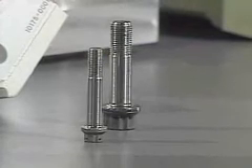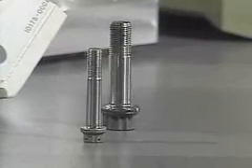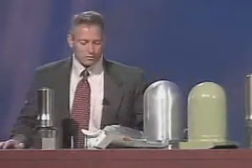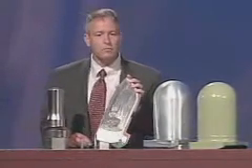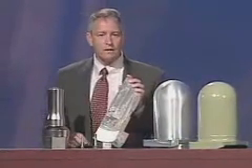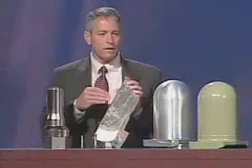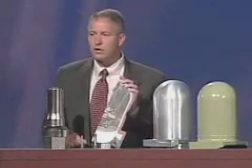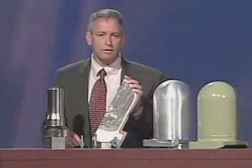So we've really done a significant amount of improvements relative to the structural capability of the bolt catcher itself. Relative to the forces that are imparted on the bolt catcher, we've done some work regarding the honeycomb material. It's an aluminum honeycomb material. We actually decreased the density of the foam in the new bolt catcher. We've gone from a 1400 psi crush strength material down to about an 800 psi crush strength material.